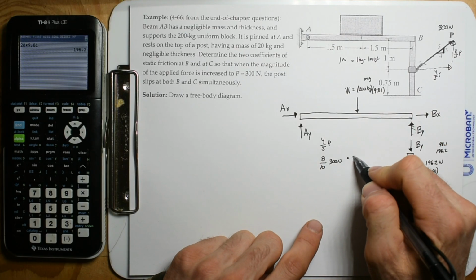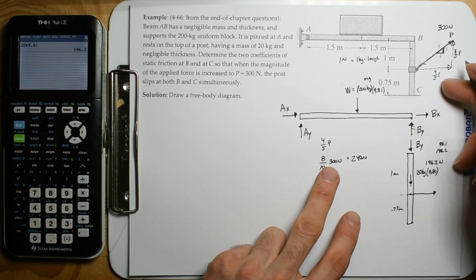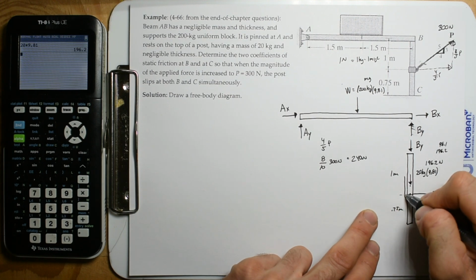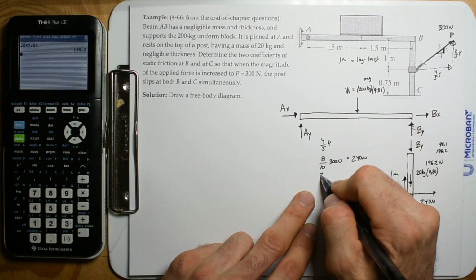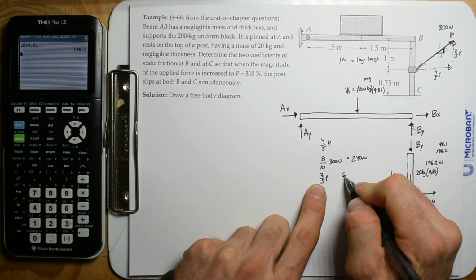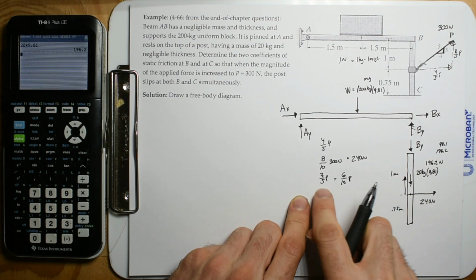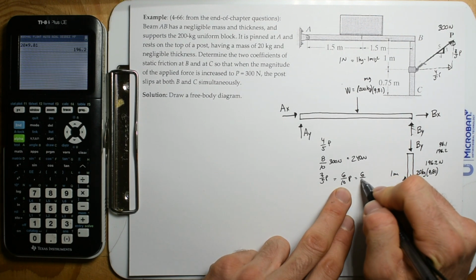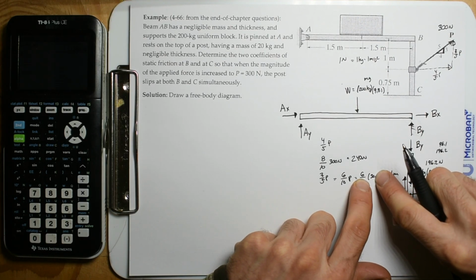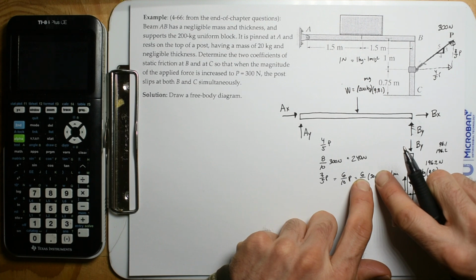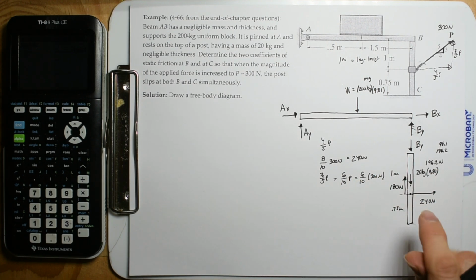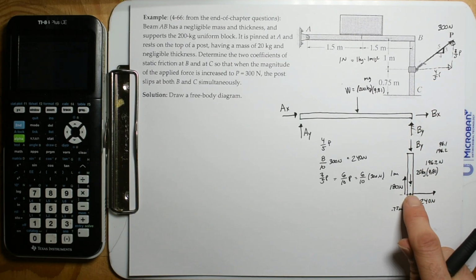Times 10 is 240. So we got 240 newtons there, and that's going to be this horizontal component. So we have 240 newtons. The vertical component of P is going to be 3/5 P. Get this denominator to be a factor of 10. That's going to be 6/10 P. These are the same ratios, and that's going to be 6/10 times 300 newtons. All right, let's get rid of the 0, and we got 6 times 3 is 18, times that extra 0 is 180. So we have 180 newtons right there. So those are the components of P, and they're acting right there.